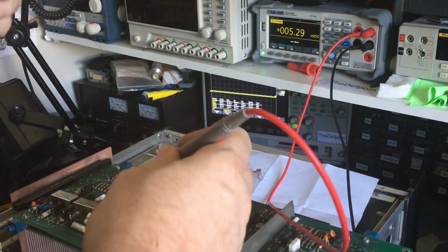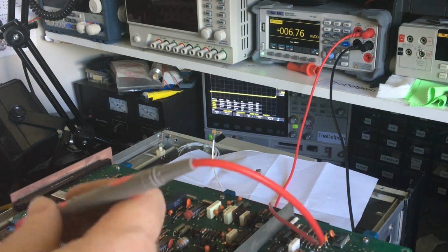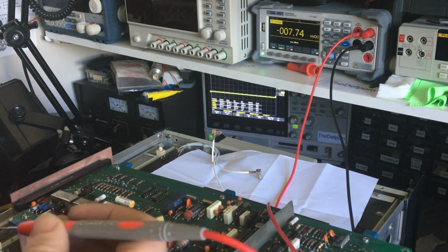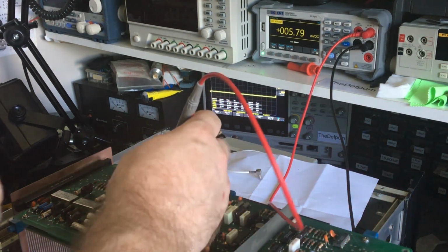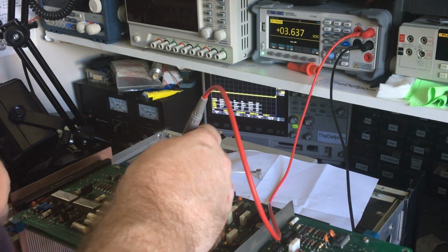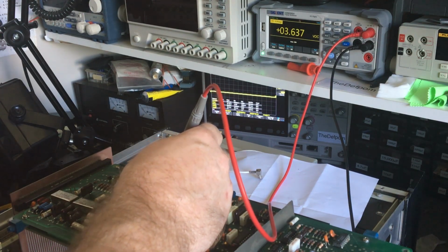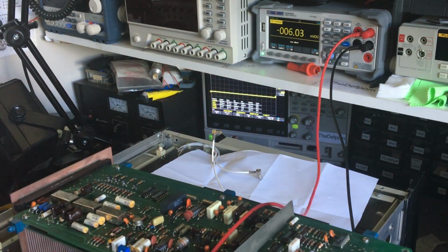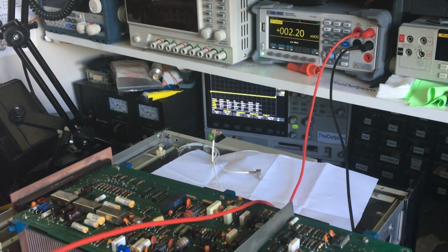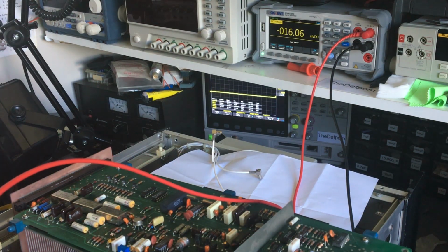So I'm on 100 hertz, set to 100 hertz. Output's currently off, but it doesn't matter because I'm just doing frequency ranges. Doesn't actually matter. 1 volt range, that sort of stuff. So let's go pin 1. 3.6 volts. 3.6 volts on pin 2. Pin 3, 0 volts. Which are correct for the 100 hertz range.